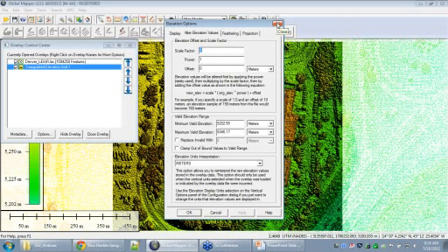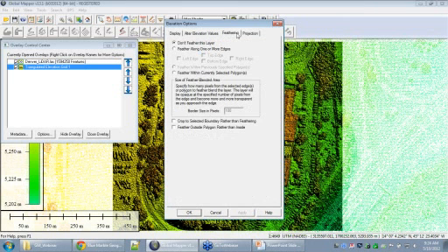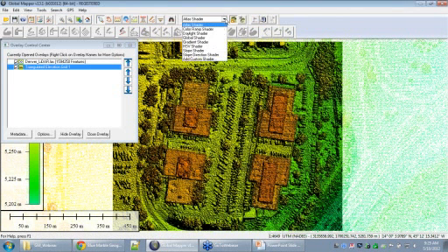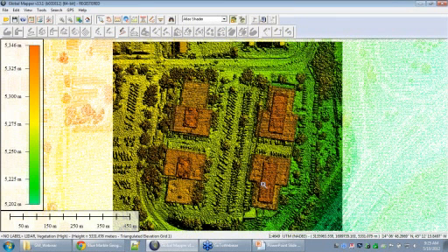So there's a number of different things we can do specifically with the rendering of those grids. And I'm going to come back in here in a minute to take a look at feathering between a couple of disparate grids, if we have grids that don't quite have the same grid spacing, if we want to smooth some of those out. So there's a host of options in here around shading. Those, again, that drop-down shader at the top, we could change that up to a number of different options to suit your needs.